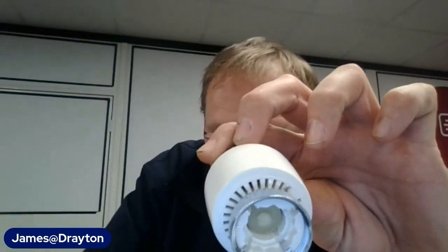So if you're fitting this in a communal hallway and you don't want people to be turning it up too high, you can pin it so that it only goes up to, say, position 3 or whatever setting you want. Similarly, if they're going into care homes and you want to make sure that you don't set the temperature too low, you can also pin it the other way. So if you start at maximum and then pin it, it means that it won't go below. You can also get extra pins, and if you put one each side of the setting, it's actually locked into position. And that's exactly the same principle that you get with the RT414.